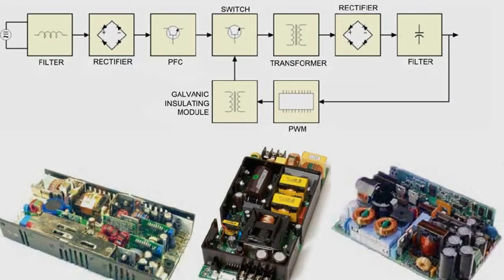Switch mode functioning. The functioning of switch converters is based on low-loss switches, which are extreme requirements for electrical power engineering. In the ideal case, when the switch is on, it has a zero drop in voltage and will transmit full energy to the load without any additional losses. If the switch is off, it has unlimited resistance, meaning that no current will go through the switch.